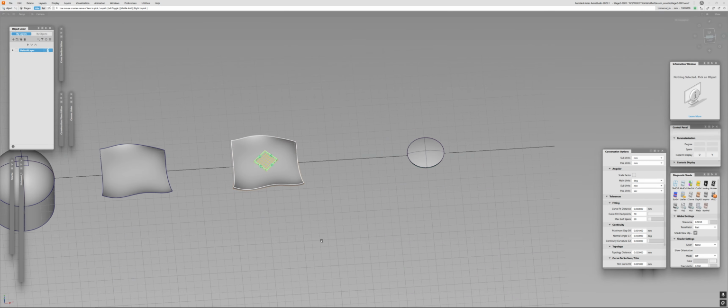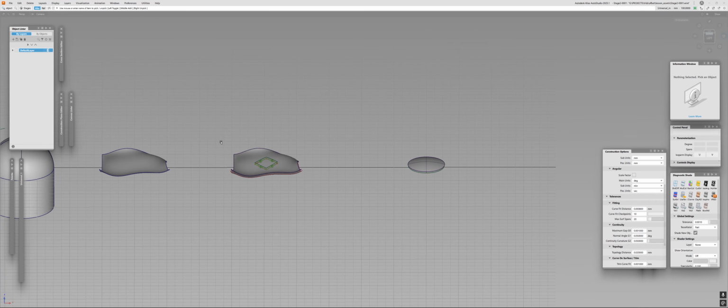So, as you're going to see, even though the offset command in Alias can give you a lot of variety and a lot of options, doing offsets for the surfaces, especially if it is a collection of surfaces, is always tricky, and it's always flawed, or like it's 99% flawed in one way or another. That's why one of the golden rules is always offset inwards.